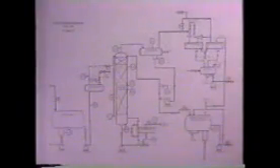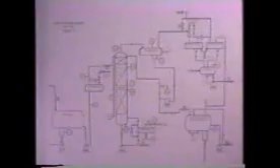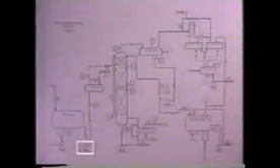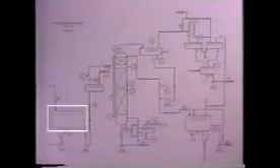Before we go on, let's go back to the graphics board again and review the last few checks we just saw. First, the outside operator selected two pumps, the reflux pump and the feed tank pump. Then the inside operator made sure there was enough mixture in the feed tank to begin the distillation process. After that, the outside operator opened the steam supply valve to the preheater.